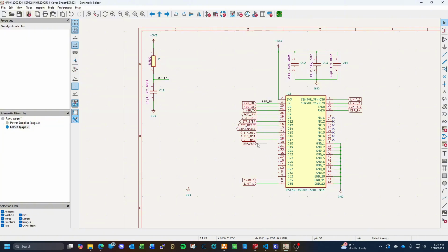Oop, connect to that pin. There we go. Okay. So that way we can use the microcontroller to observe for a fault. Like I said, it won't tell you exactly what the fault is, but it'll tell you if the stepper driver is saying there's a fault condition, if you want to monitor for that kind of thing.